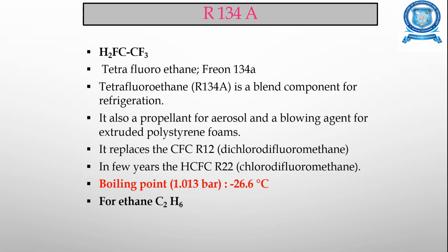And R134A, CH2FCF3, tetrafluoroethane, also called Freon 134A, is a blend component for refrigeration. This can also be used as a propellant for aerosols and a blowing agent for extruded polystyrene foams. It replaces CFC R12, dichlorodifluoromethane. And in recent years, HCFC R22 has been used, and its boiling point at 1.013 bar is minus 26.6 degrees Celsius.